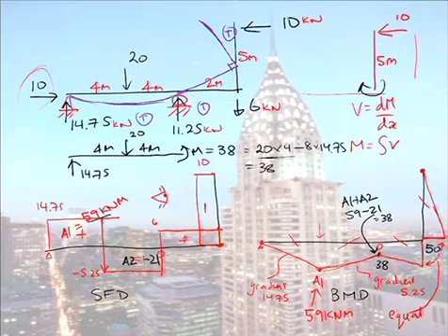When I said in the previous problem about superposition, yes, there's a 6 kilonewton here, but it's not a big enough load to pull it down such that you'll get a point of inflection anywhere. So this is moving down because you have the 20 kilonewton, and because you have a horizontal 10 pushing it inwards, you're still getting that tension on the bottom throughout. So there's the deflected shape.